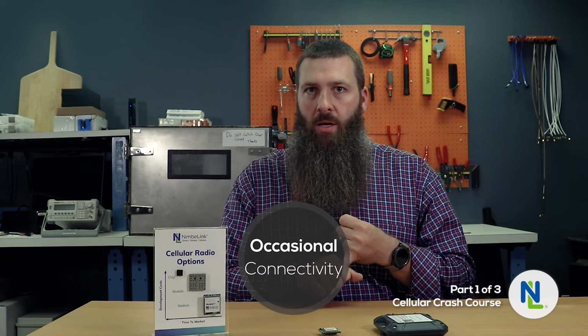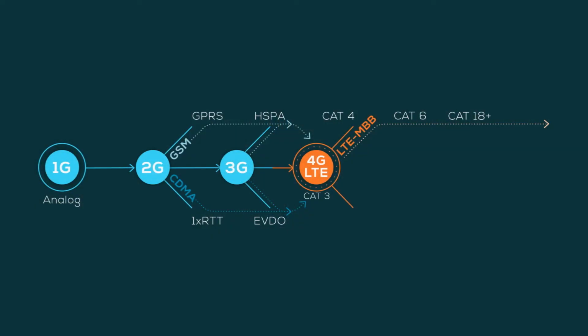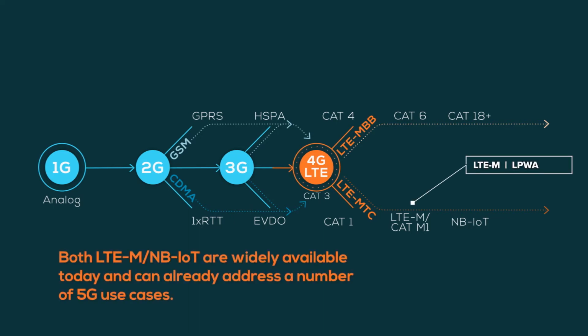And then you had devices like our IoT devices that really didn't need all that. We needed occasional connectivity, we needed low power, we needed low cost, we needed simplicity in the radios. And so a whole different path was created, which is the MTC path, or machine type communications path, where we kept getting simpler and simpler, eventually leading to things like LTE-M, or LTE Category M1, as it's sometimes called, and then NB-IoT, or NB1, and then NB2.